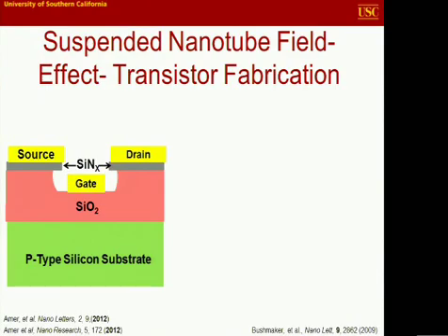So the ones on the silicon nitride are going to act as the drain and the source, and the one in the middle of the trench is going to act as a gate. And then we pattern catalyst windows on top of the drain and the source, and these catalysts are going to stimulate the growth of carbon nanotubes, which actually happens at 125 degrees Celsius.